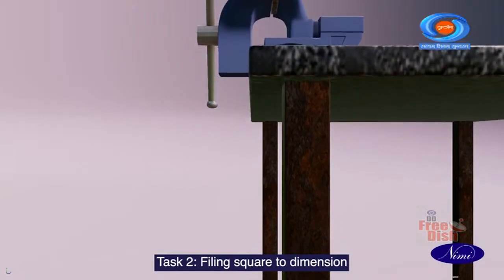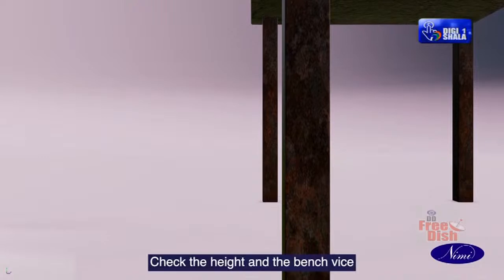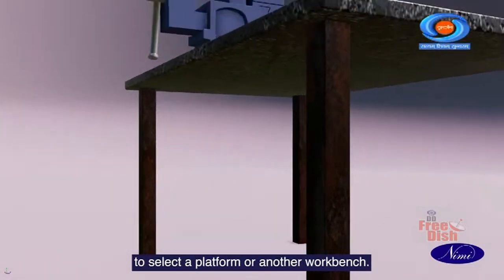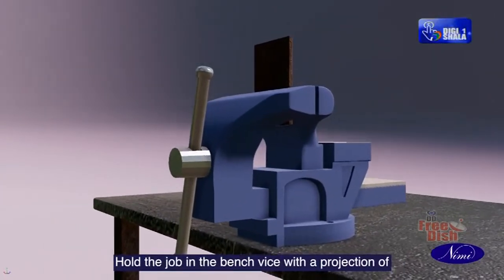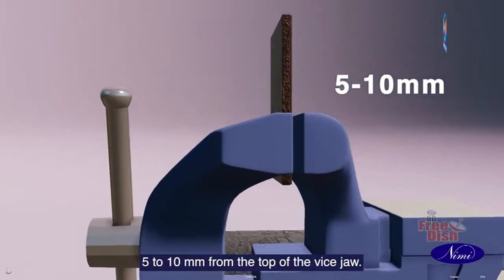Task 2. Filing square to dimension. Check the height of the bench vise to select a platform or another workbench. Hold the job in the bench vise with a projection of 5 to 10 mm from the top of the vise jaw.